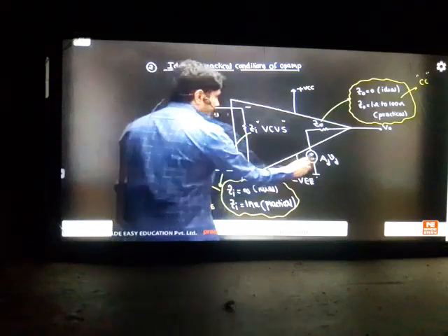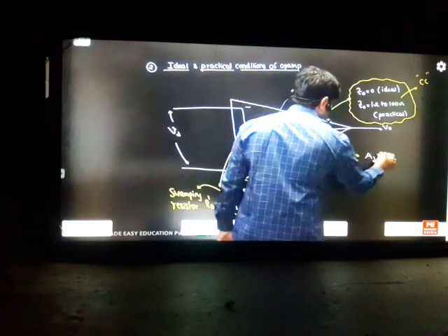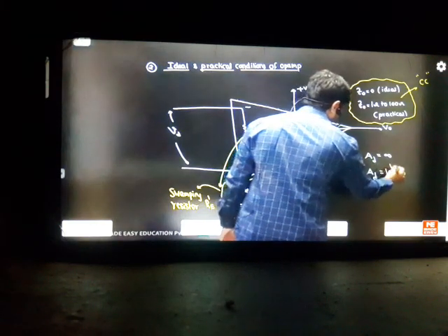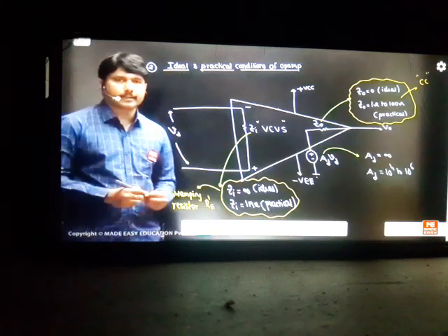Coming to the next beautiful concept, the AD concept. Each and every reason I'm teaching from the differential amplifier knowledge. How to take AD here: your differential gain should ideally be infinite, but practically we are getting 10 power 4 to 10 power 6. If I use 2 differential amplifiers in cascade, 10 power 4 is coming. If I use 3 differential amplifiers, we are getting 10 power 6.